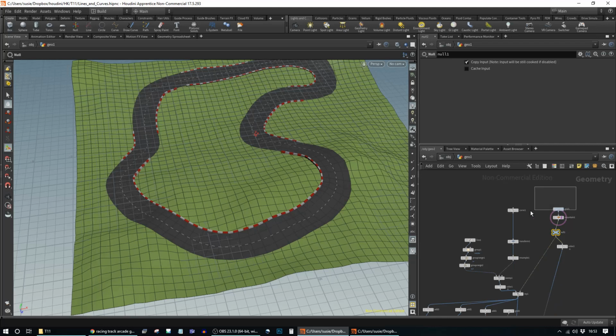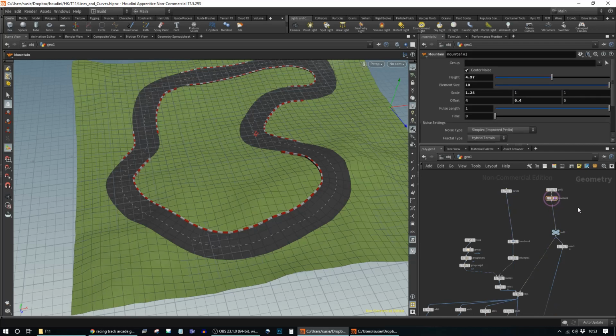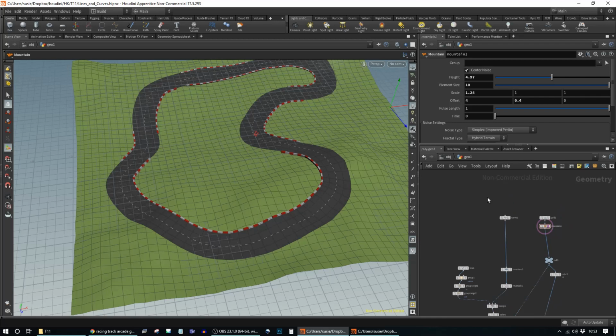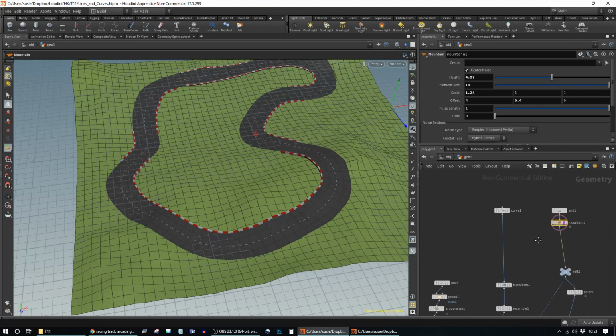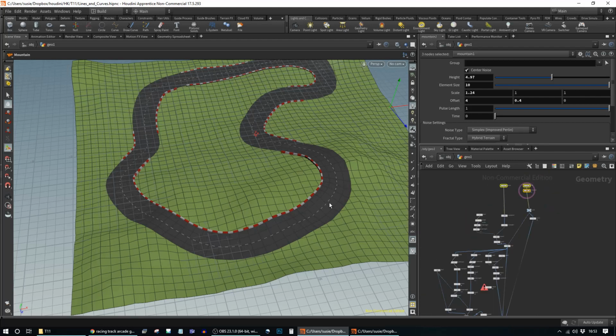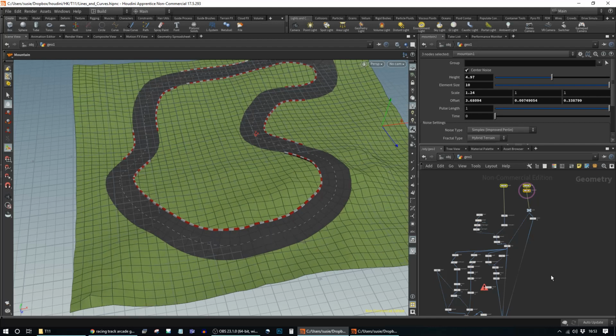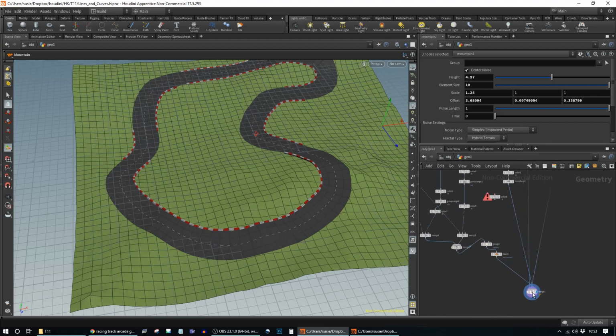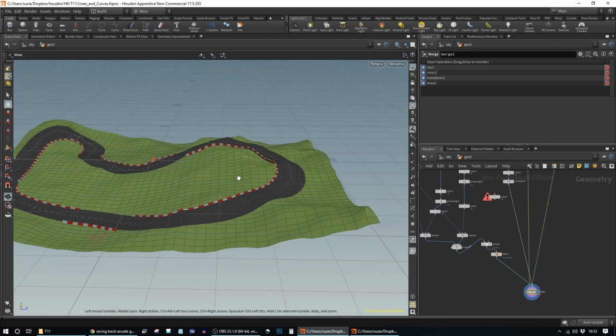Unreal will let you add a curve to a Houdini digital asset, and you can also add a surface. So we could have these being created by the game designers, and then this tool would simply place the track where the curves go and correctly put lines down the middle and barriers and things. So you can see how useful this would be for quickly generating geometry that was consistent.